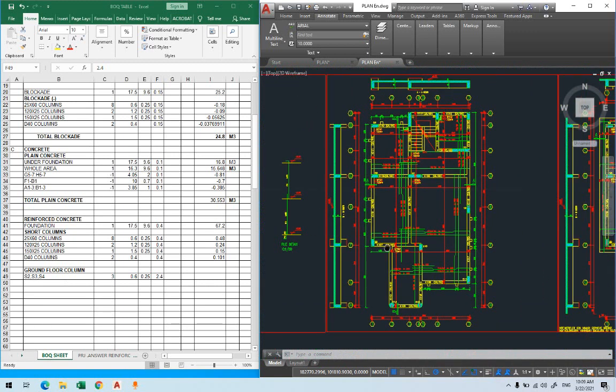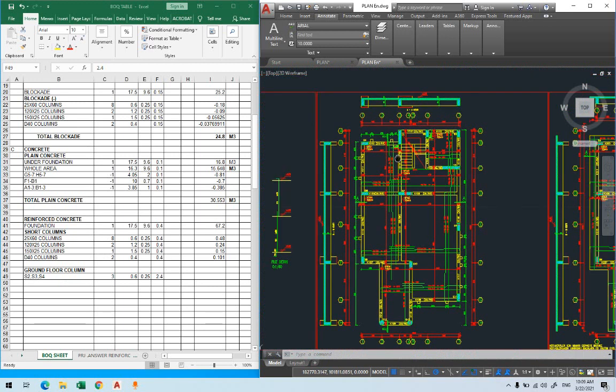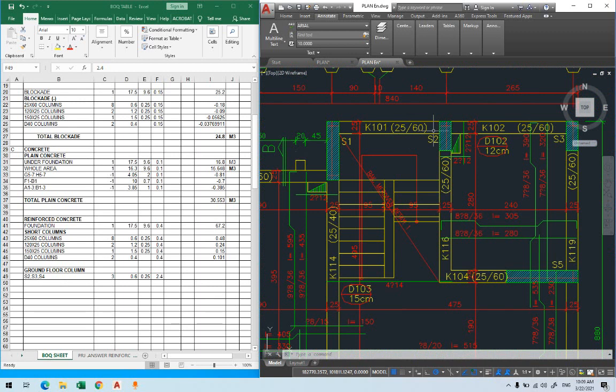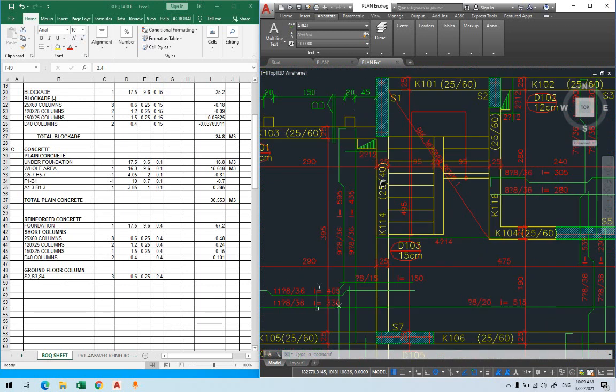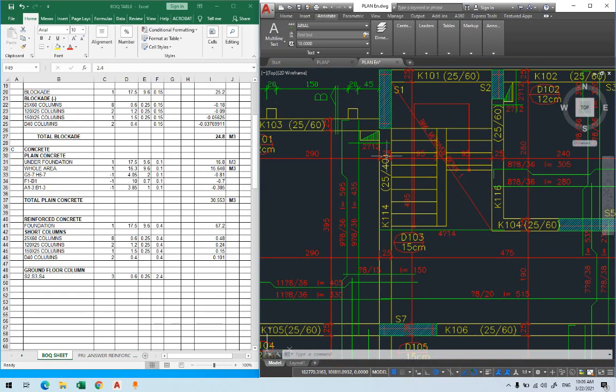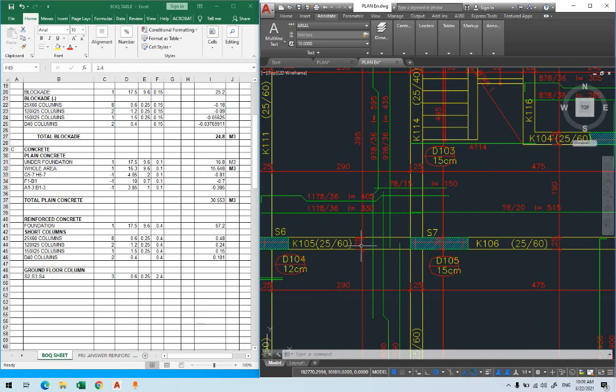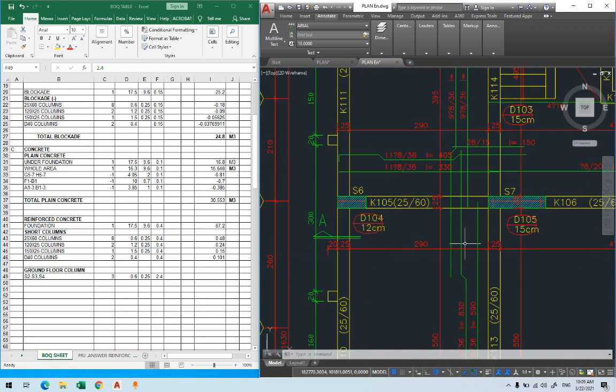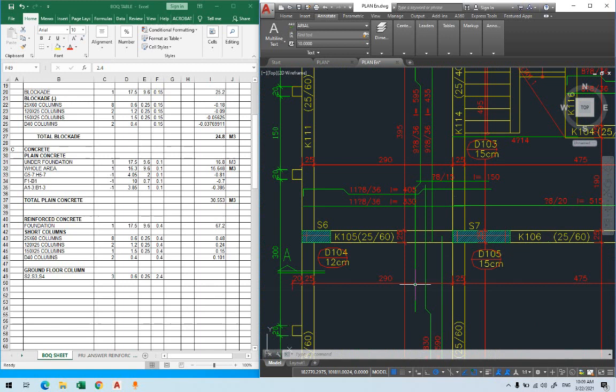How can I do this faster? I can check the beams in the first floor. Roughly check all the beams: 20, 60, 60, 60, 60, all the beams except this one here, it's 40 here. But again, the highest is 60, I have it here. So still I'm on the safe side because I'm looking for the deepest beam. This is 40, I have 60 here, no problem, 60.